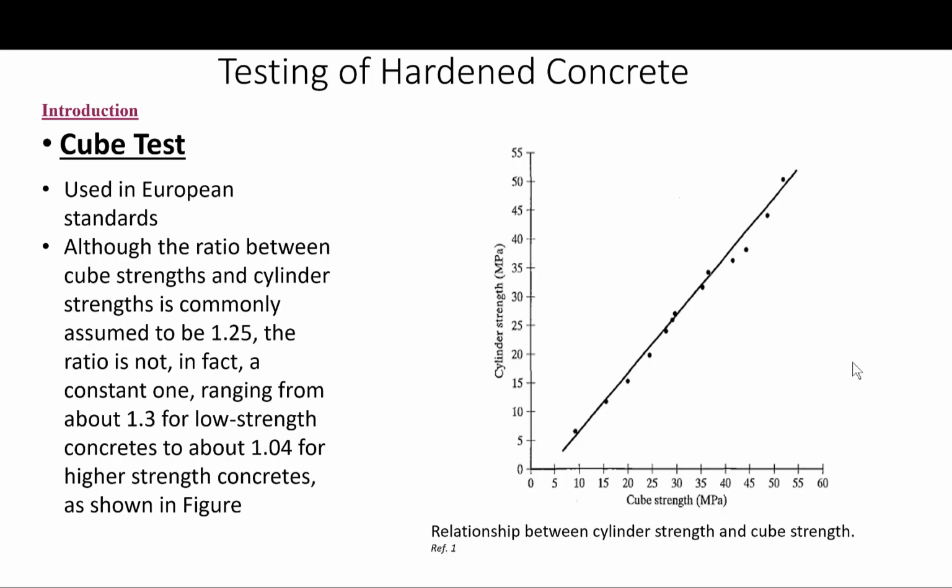I've seen concrete professionals use this ratio. Although some standards report a ratio, I will not use a ratio arbitrarily unless there is evidence this ratio has actually been calculated from actual data on the concrete I am using. So that's something I have to warn you about.